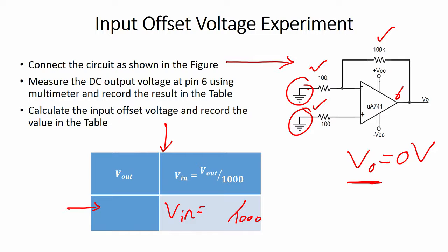So, let us see this actually in the experiment. We will take our operational amplifier and 3 resistors of this value, connect them, and let us see the output voltage initially. We will understand that we will not see this output voltage as 0 volt in a practical op amp; we will see some millivolts. So, let us see this experiment.